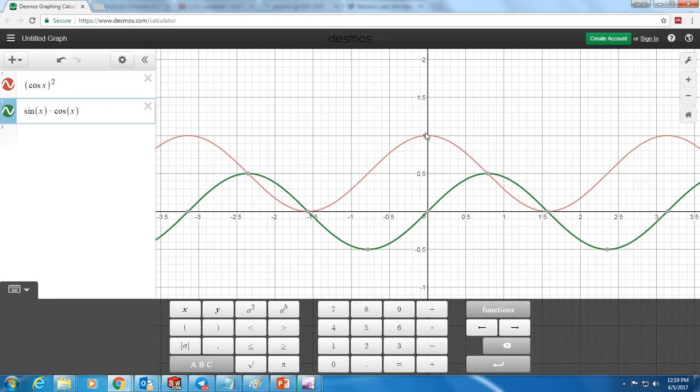The second part asks at what inclination angle the shear stress is maximum. We can see at this angle and this angle, and you can find their equivalent value, for example pi over 4 or minus 3 pi over 4, so 45 degrees here.